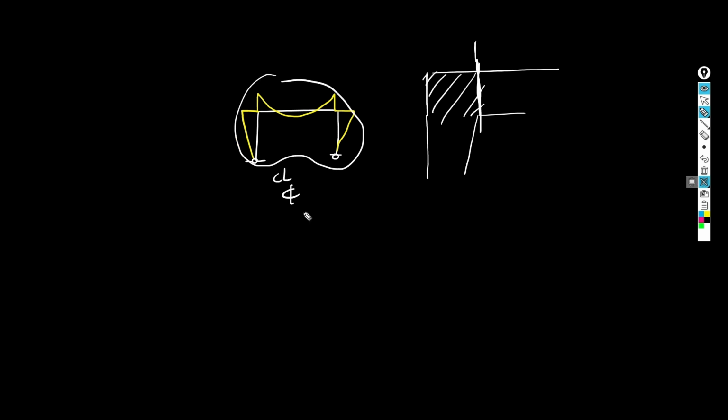So what happens is, this is drawn by center lines, right? So you're drawing using the center line method. Now, what actually happens is that the column has a thickness, and the beam has its own thickness as well. So this region, right here, has a huge depth. So I'm not really concerned about the moment on this one. I'm concerned about the moment about this section right here. So what the program does is start calculating the moment from this side. So the moment diagram is not going to look like this at the end. It's going to look more something like this.